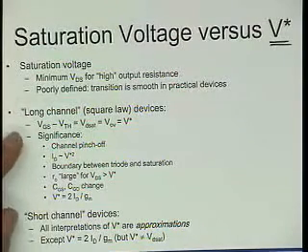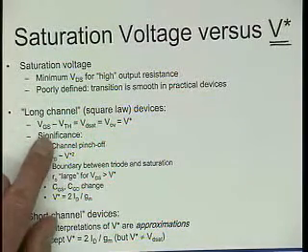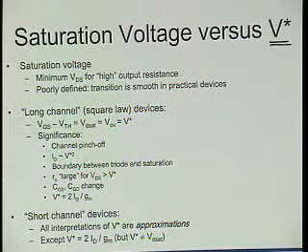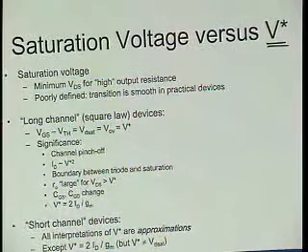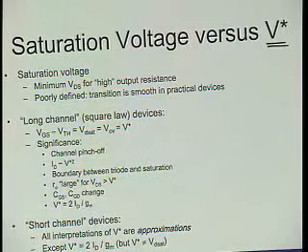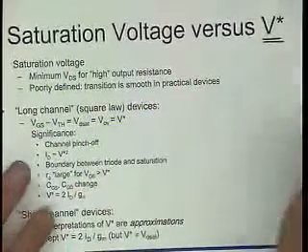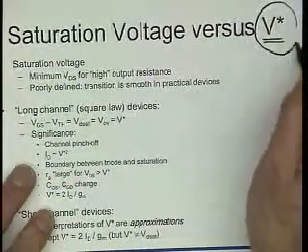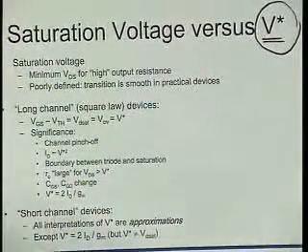The other thing is that this VDsat is VGS minus VTH. It also is the proportionality factor that, when squared, tells us how much current we get at the drain if the transistor is in saturation. And it's a whole sort of other things, right? Well, in real transistors, these just diverge. These are all different numbers, right? And so V star is, in a way, just one meaning of all these.